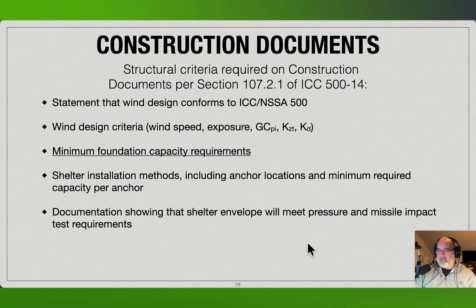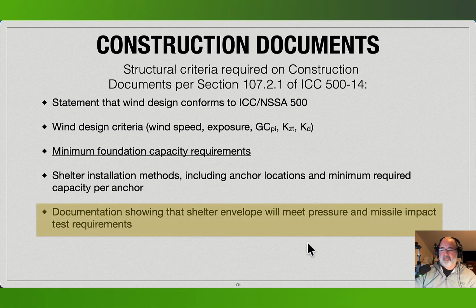Minimum foundation requirements, shelter installation methods, including anchor locations, minimum required capacity per anchor, and then documentation showing the shelter envelope must meet pressure and missile impact test requirements. Obviously, that's going to be important to use approved systems.